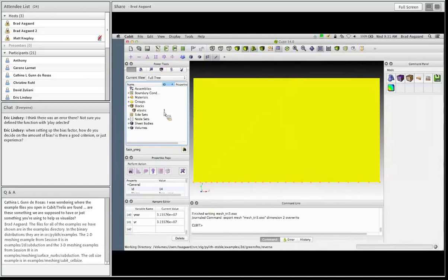That's because we had a geometric constraint: we had this layer that we were meshing separately, and our discretization size was starting to get larger than the thickness of that layer. So in that case, we were starting to get distorted cells because we were coarsening and trying to impose a discretization size bigger than the size of our geometric feature.